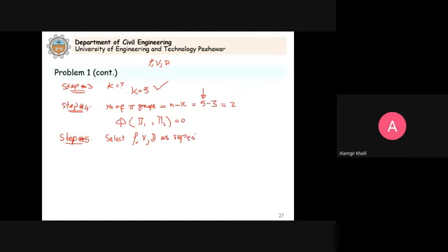Now the question is, will these always be the repeating variables? No. Will you always select rho, V, D as repeating variables? No. When we finish this problem, I can tell you that if I take other than these as repeating variables and solve the problem, you should still get the same result, but the functional relationship will not be exactly the same.